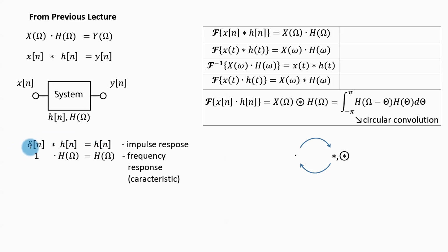When you take this equation into the spectral domain, you get this. The Fourier transform of the Dirac delta pulse is 1, and the Fourier transform of the impulse response is the frequency characteristic. So, by feeding the Dirac delta pulse into the system, in the spectral domain, I'm actually feeding the system with all the frequencies. So, in the output spectrum, I will see how the individual frequencies are being passed.